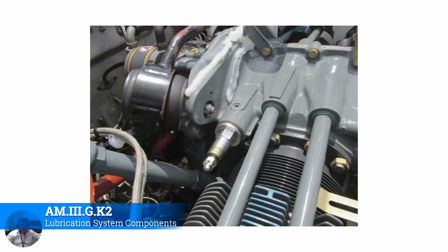Okay, the other one is your pressure regulator or your pressure relief valve. This is how you will adjust the engine oil pressure. What you can do is take that nut off and put washers on there. Some of them, however, you can adjust with a screwdriver, depending on the model of the engine. So you'll always want to go off of whatever the maintenance manual tells you to do to increase or decrease the engine oil pressure.